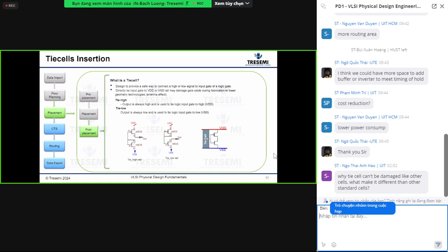As you can see, the gates are tied completely. In the regular cells, the gate is not; it's actually tied to the drain, and then there's a path to the ground. So it has a discharge path from any antenna effect, for example the plasma.